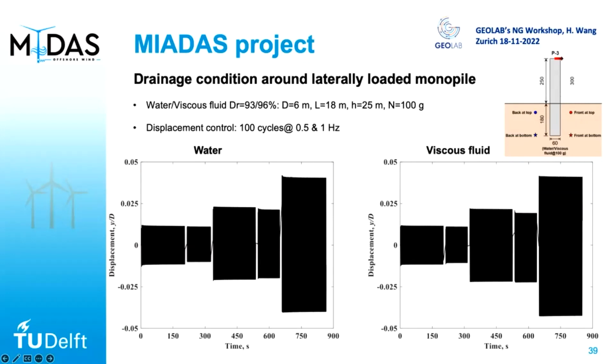Yeah, in reality. But 0.01 hertz would be 10 hertz in the centrifuge, no? We did the test at 50 g, so, yeah, this one is 100. Yes. So if we scale, that should be 10 hertz, and we did only 1 hertz here.